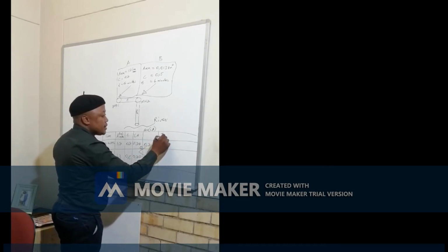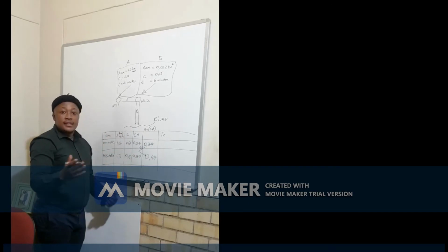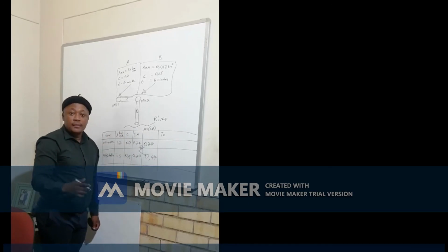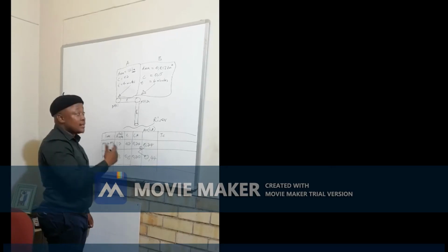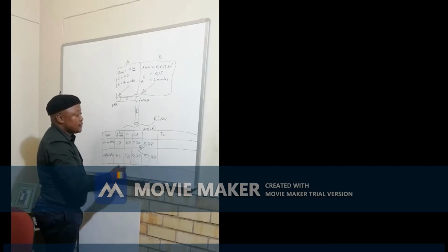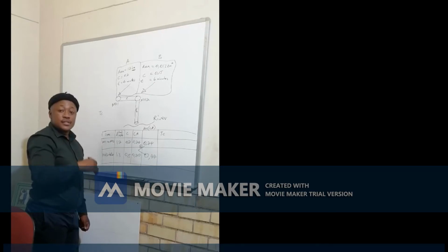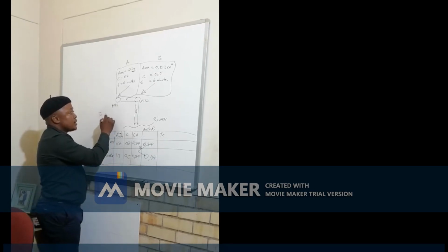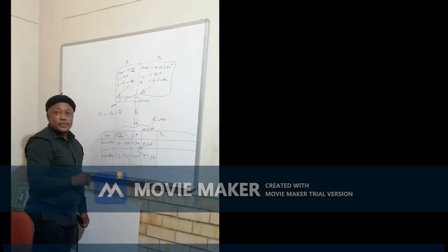Now this one here is the time of concentration, but bear in mind here that when you deal with this, there is a procedure that we've shared in one of our previous screens, the procedure for the calculation, whereby it gives you the columns and what is expected in each column in terms of calculation. But now the time of concentration is no longer calculated in the context of the formula, but it's also established through the inlet time plus the time of flow, which is very important.